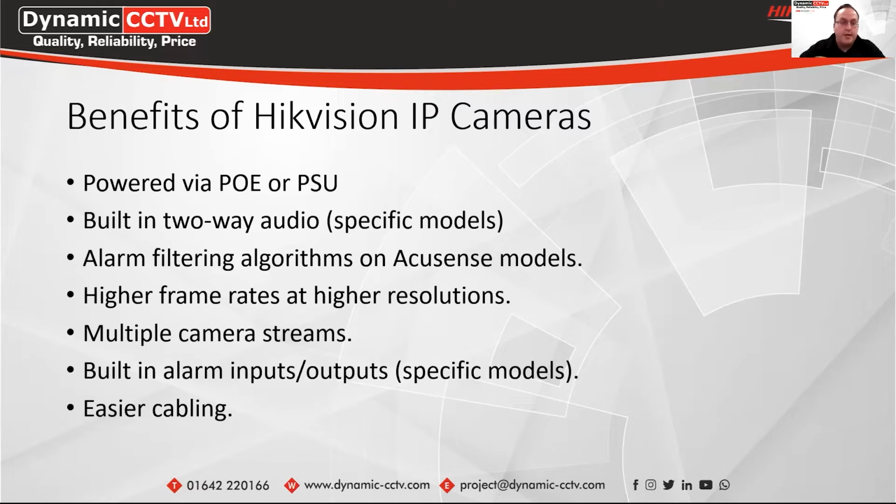You can also have multiple camera streams from an IP camera. So in the days of the analog recorders, and there's still a TVI recorder available currently, if you wanted to have another recorder in a separate location, with the physical connections of TVI and analog technology, you'd wire your cameras into the back of your first recorder, and they'd have a loop output which would repeat those camera signals, and you'd take another set of cables to your second DVR, which is in another location.